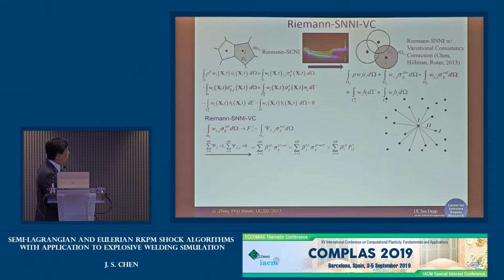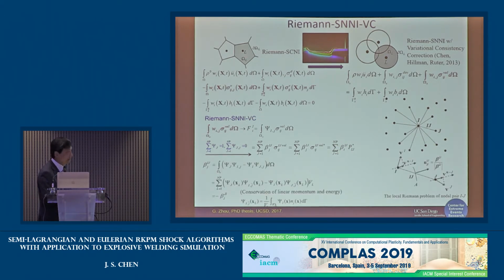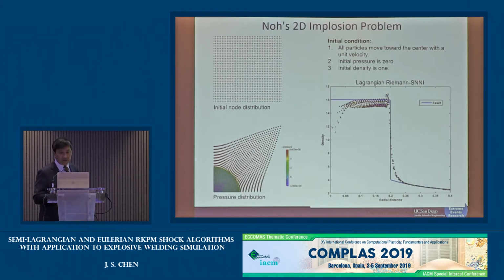And so it'll be pressure between point i and point j, and then this geometric parameter beta ij, and through this consideration, beta ij will look just like this, and the gradient of the shift function again is computed by this contour integral, right? And the Riemann condition is now imposed in the middle. Okay, so with this we have a few test problems.